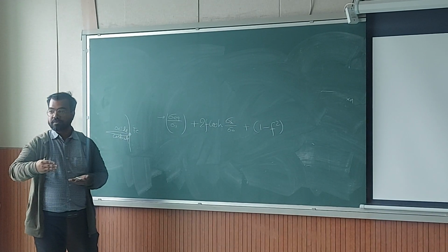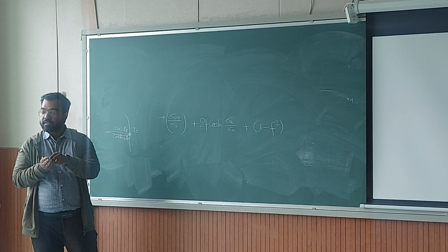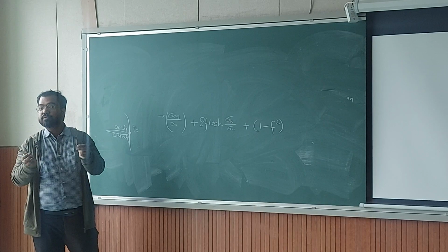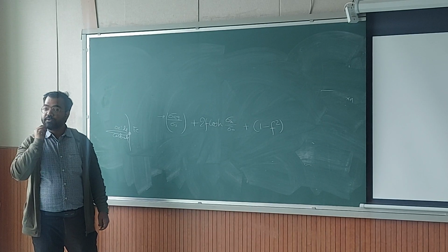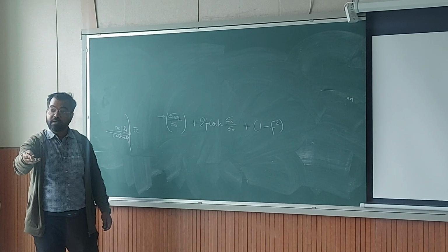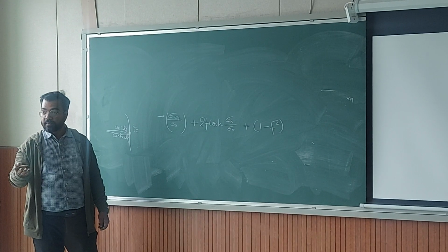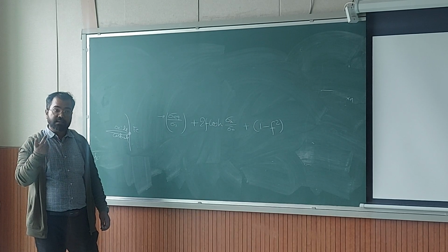in every stage will be decreasing the yielding, because if the amount of force which was needed to yield at, let us say, the ith iteration, you don't need that much force to yield at the next point when you have more void, because the load bearing capacity of that representative element has decreased.